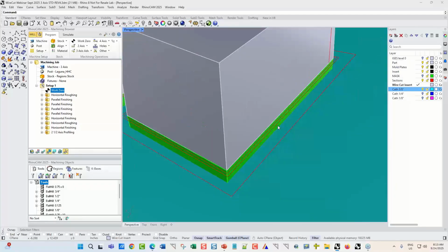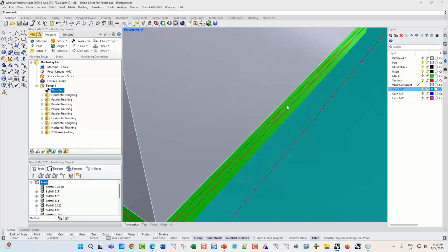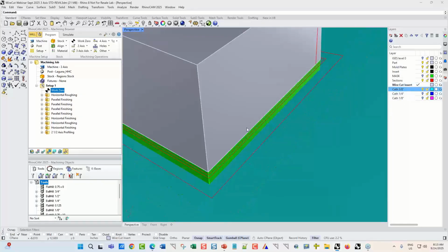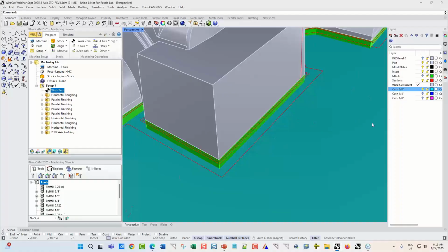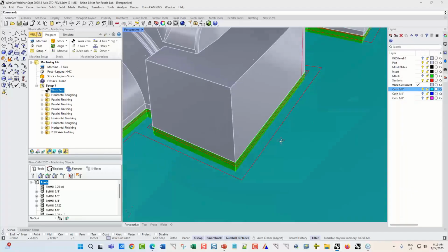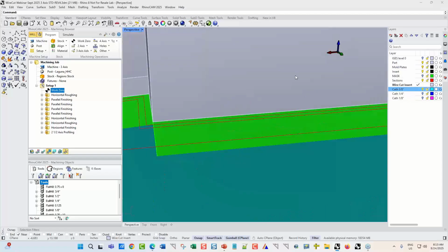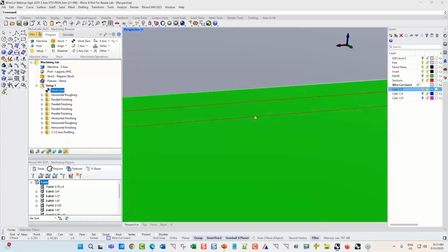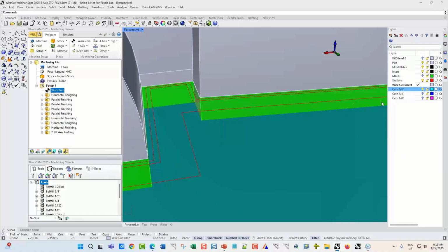As you can see here, we've got some offset curves we're going to use for different tool sizes. So this catch plane, catch 3/4, which I spelled wrong, means the 3/4 ball mill is going to stop on this plane, which is 3/8 of an inch below the parting plane. So the tangent of that ball mill with this catch plane is going to hold that tangent right on the parting plane. Okay, so you've got different planes for different ball mill sizes.